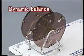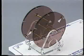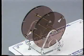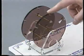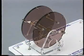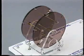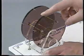Now let's see the dynamic balance. The tire has thickness, so let's suppose that heavy spots are located inside and outside the disc assembly. In this case, the disc assembly can stand still at any position. In other words, the disc assembly is statically balanced.